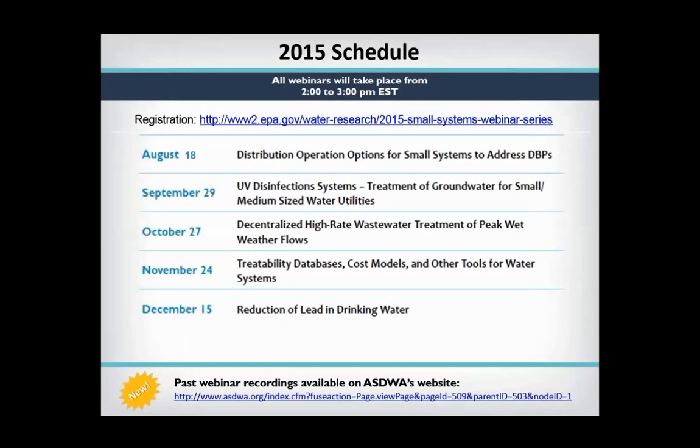Chances are it's primarily a pH problem if it's a negative Langelier index, just because the main parts of that index are the carbonate concentration, the calcium, and the pH. So I would say go back and look at what the pH and alkalinity of that water is, and whether or not they're adding phosphate or something else in the background that also could be a factor in inhibiting the passivation of the copper.